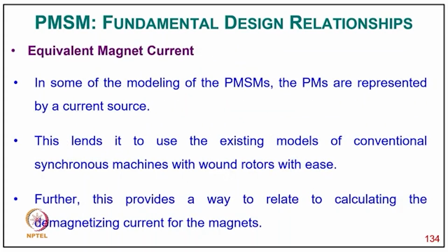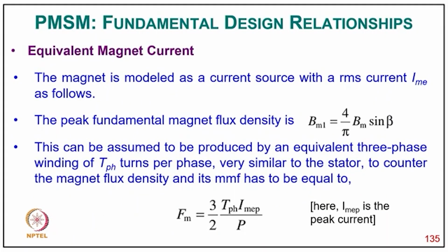So in some of the modeling of the PMSMs, the PMs are represented by current source, and this lends it to use the existing models of conventional synchronous machine with the wound rotor with ease, and further this provides a way to calculate the demagnetizing current for the magnet.